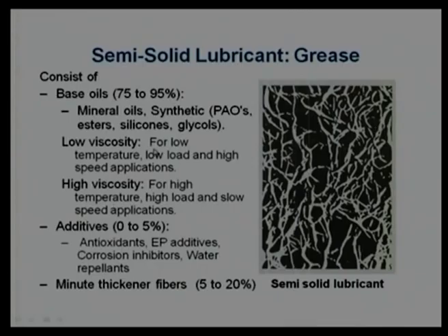When talking about low viscosity, generally they are used for low temperature, because with an increase in temperature we know the viscosity will decrease. That is why at high temperature we use high viscosity oils, because as the temperature increases they will turn out to be a low viscosity oil at high temperature.